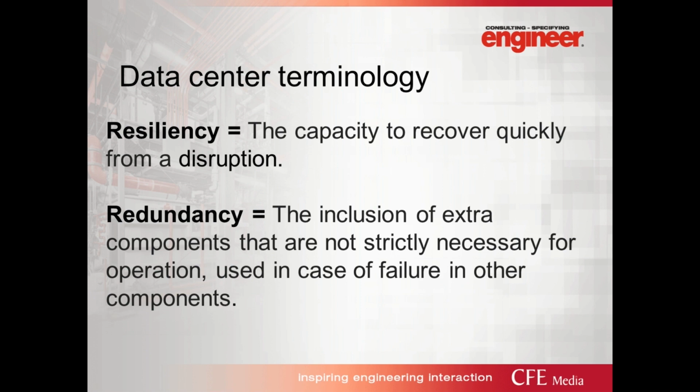Redundancy, the inclusion of extra components that are not strictly necessary for operation, but used in the case of failure of other components. Obviously, uptime is the first thing that comes to mind, but oftentimes what I'm seeing is it's more used in scheduled maintenance. Being able to de-energize or remove a component from your system for proper preventative maintenance so that you can be proactive on the health of your system.